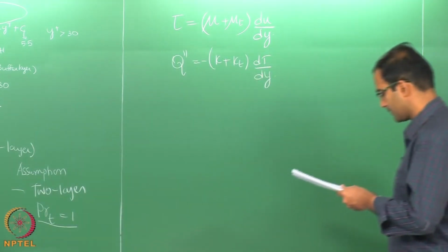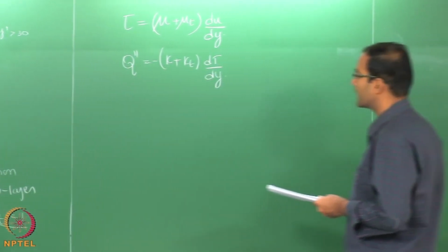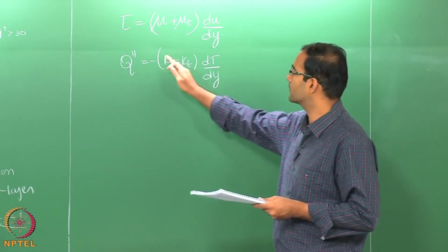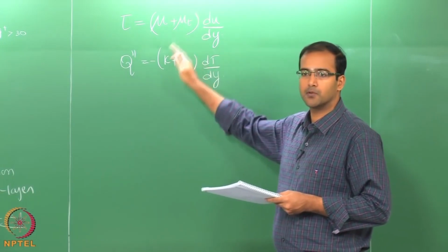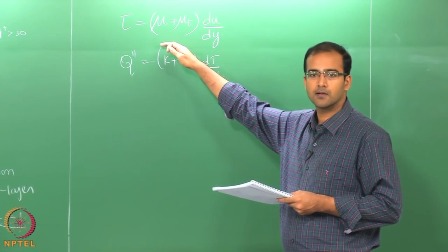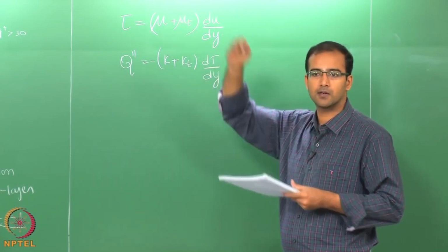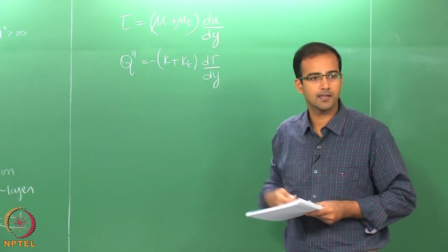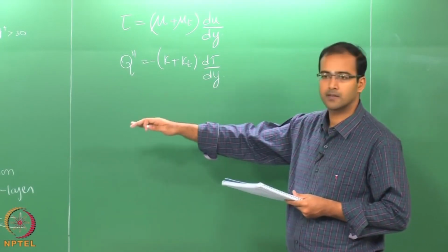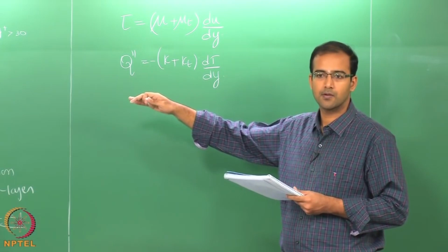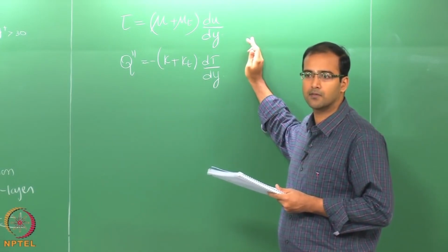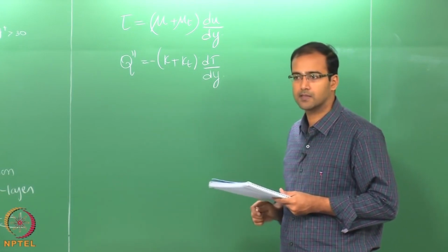If you are looking at Reynolds analogy, it assumes fully turbulent flow. Therefore, we neglected mu compared to mu t, k compared to kt, and then we integrated from the wall to the boundary layer and divided one over the other, and then we ended up with this. Now we have divided this into two regions. We will first apply this for region 1, which is the laminar viscous sublayer.